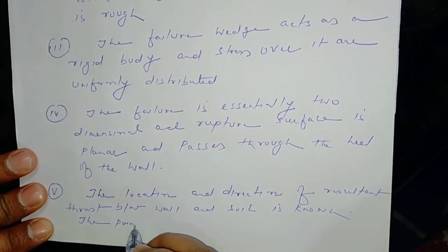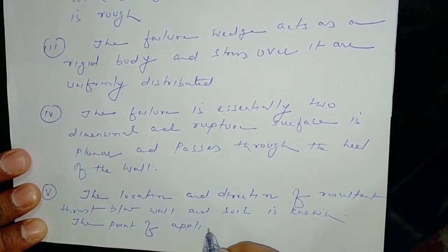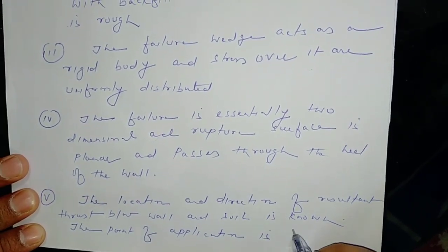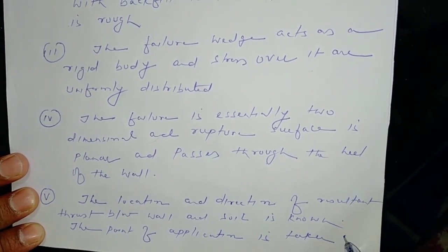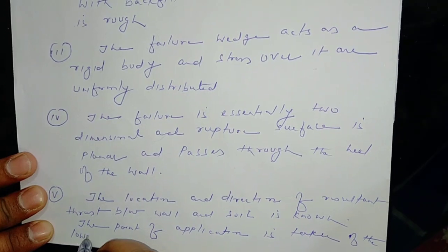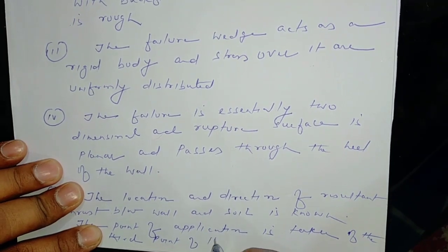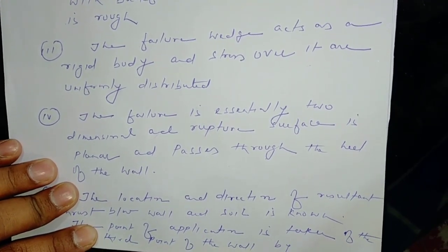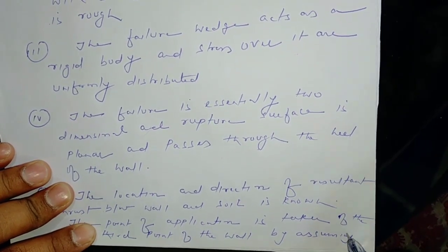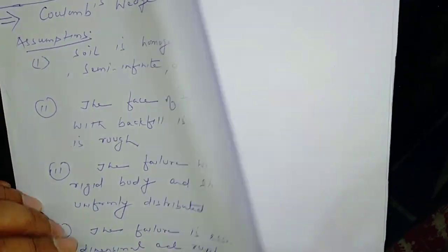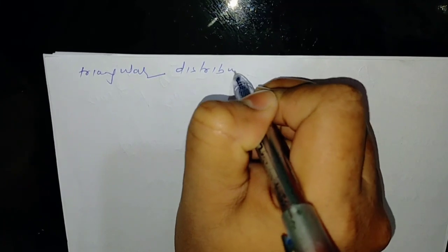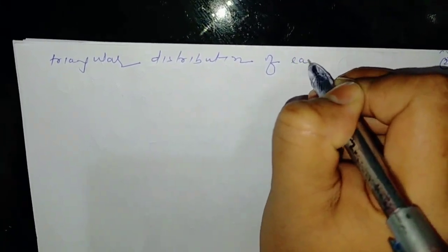The point of application is taken at the lower third point of the wall by assuming a triangular distribution of earth pressure.